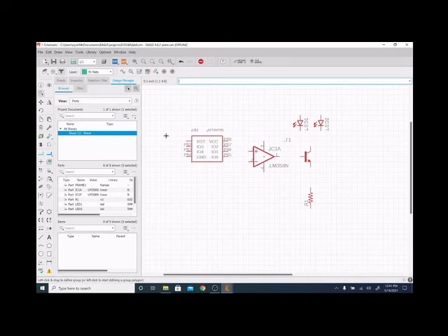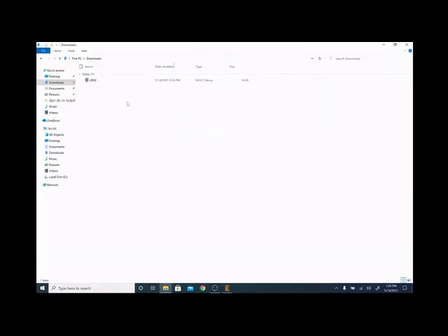And to get this, we're going to import a custom library that will be available on Learning Suite under the Lab Resources tab. Alright, so I've downloaded the library from Learning Suite. I'm going to right click here and copy, and then I need to navigate to my Eagle library folder. That's in documents typically, and then you go to Eagle and then libraries, and then I can just right click and hit paste. You can see that library shows up.